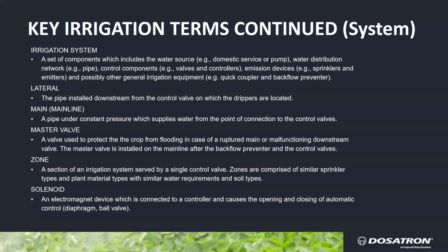A main line will typically have a master valve on it, and the master valve is used to prevent any kind of flooding or overfilling of a tank. And it usually turns on in conjunction with a zone valve. A zone valve is a valve that's placed at a grow area, and that zone is going to turn on through the use of a controller and water for a specific amount of time, and then it's going to turn back off. When we turn on a master plus a zone, we're then allowing our source to reach our destination.